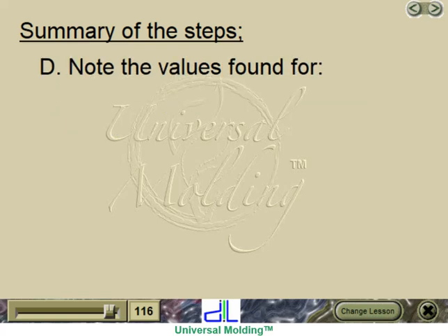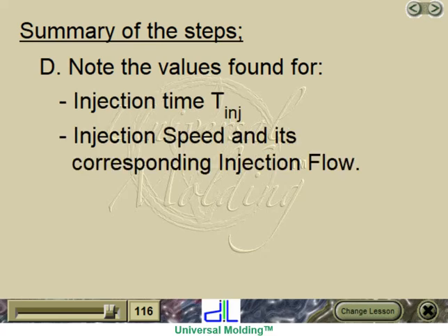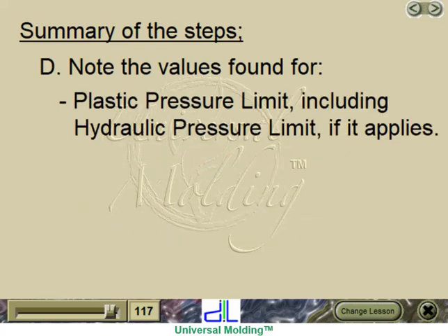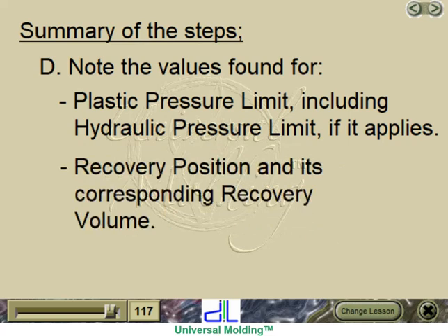D. Note the values found for injection time, injection speed and its corresponding injection flow, transfer position and its corresponding transfer volume, plastic pressure limit, including hydraulic pressure limit if it applies, recovery position and its corresponding recovery volume.